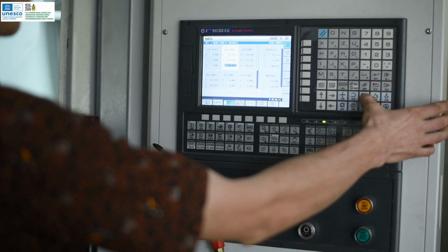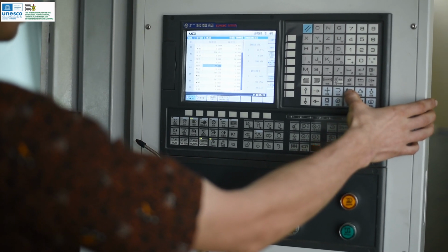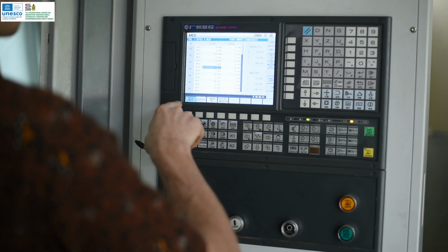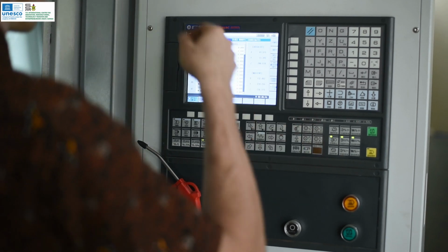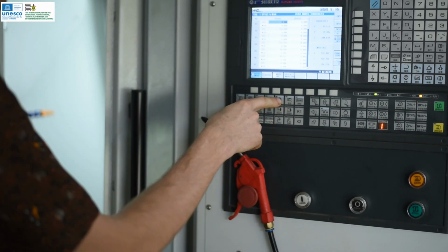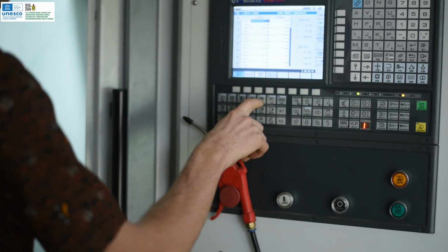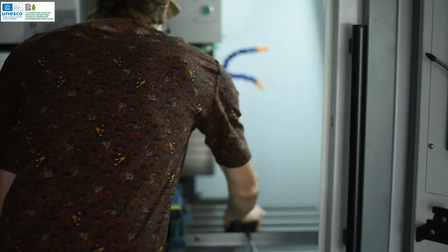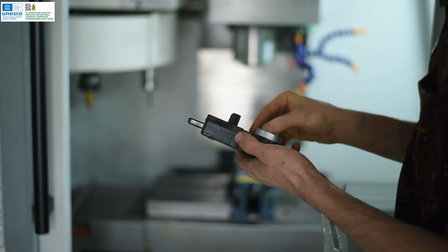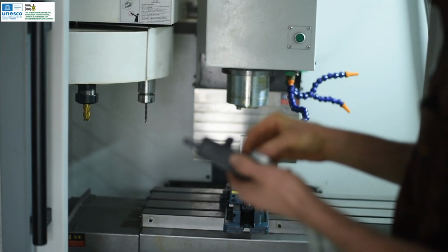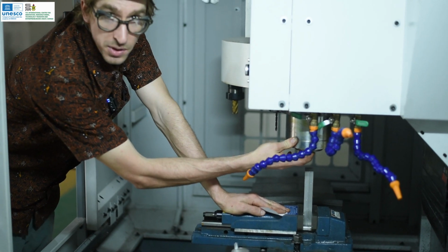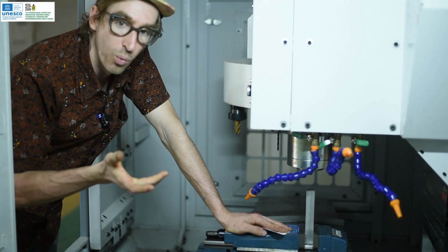So we'll go to our tool offsets. Tool offset button here. And jog up to T0. And we'll use our hand wheel by selecting the hand jog button here. And with this set to Z, we'll move our spindle down close enough. With no tool in the spindle and the tool changer saying tool 1 in our case,